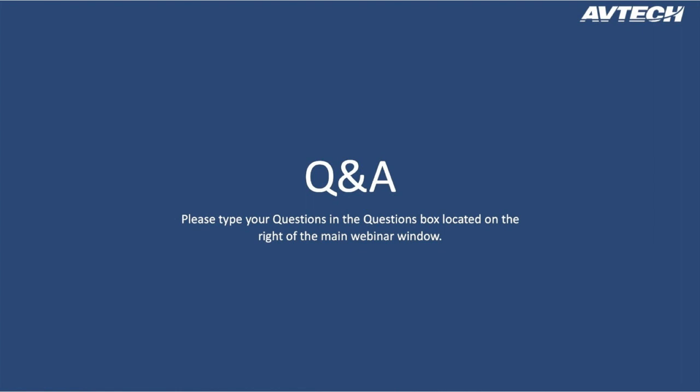Next question from Carlos. Where does the ACARS uplink generate from? So AVTECH, as mentioned, we have our own ground address in the ACARS network. So we can either directly uplink from our address to the airplane. We have some airlines that pick this solution. We can also connect directly to the airline and provide the uplink in any type of format via the internet or ACARS, and then the airline can provide it as part of its EFB package, integrated in its EFB solutions, or uplink it themselves to a printer or display in the cockpit.